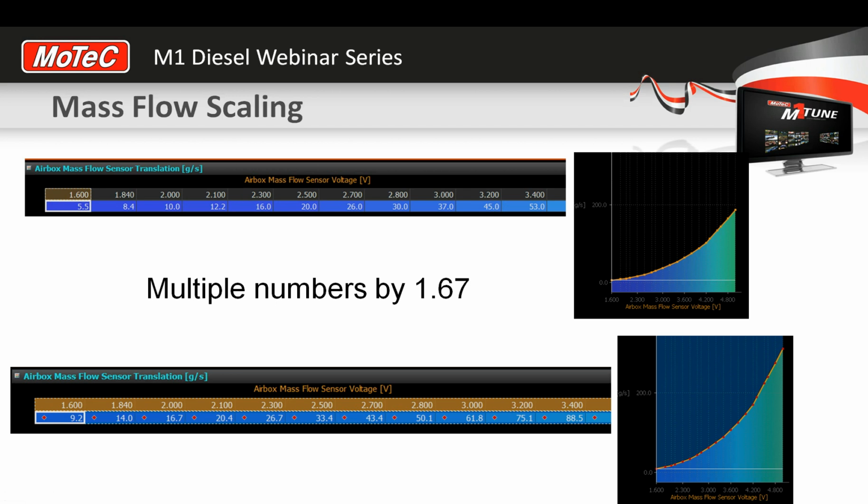The other method is if you do have the luxury of having a standard vehicle that you're working on with an OBD2 port. Any late model vehicle today has OBD2, and you can just pop a scan tool into that socket, and in most cases you can see what the airflow meter output is.